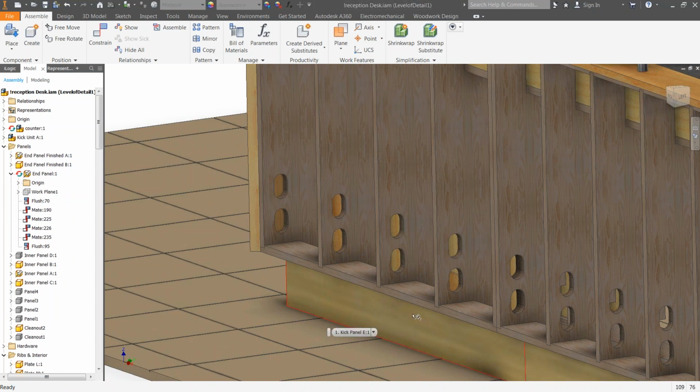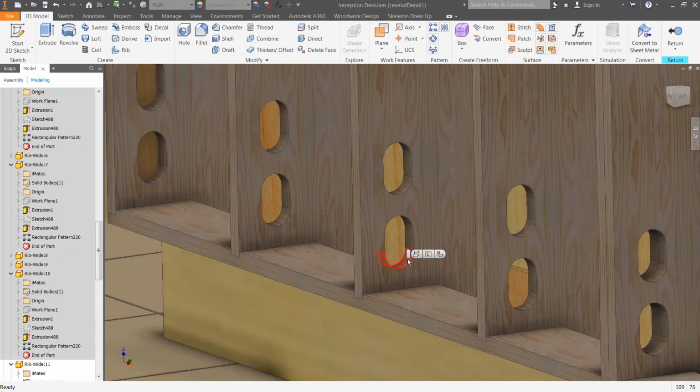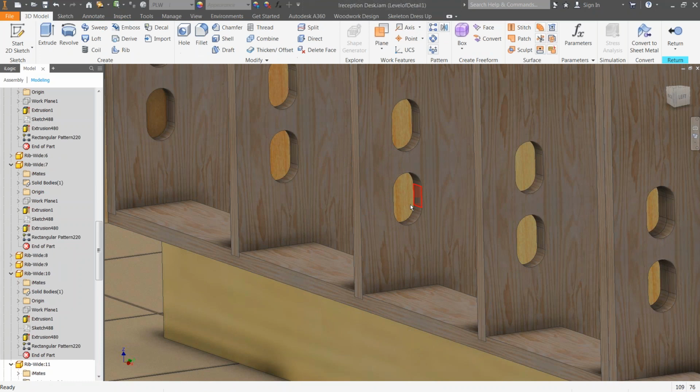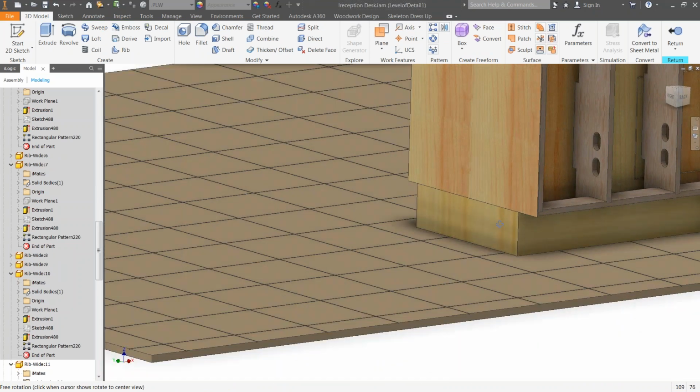Now, let's say that he said move it 2 inches up. That means you start a project, and after it's halfway done, there's somebody else who's going to change it. So to do that, again, all I'm going to do is touch the cutout, tell it I want to edit what was done. I'm going to change this to 5 inches, no, 4 inches. Let's go 2 inches up, and let's go 2 inches over. That's 2.5. And then I'll say finish and everything adjusts. Now, on top of that, let's say that we needed to cut through the side.